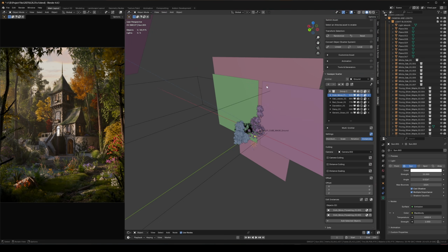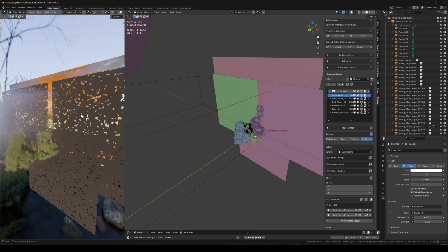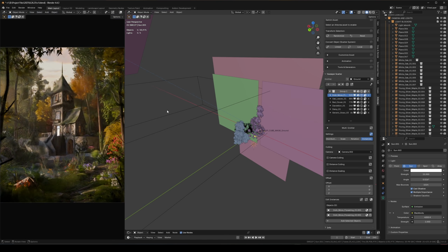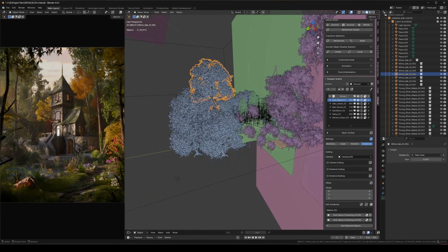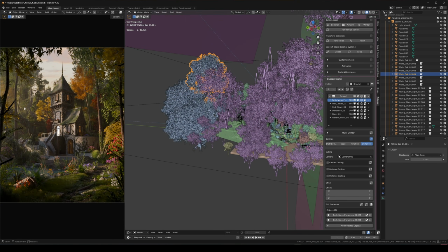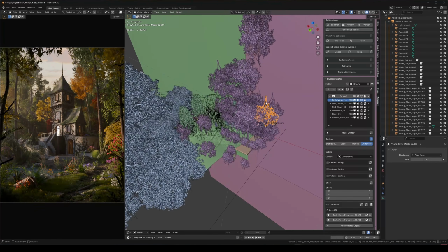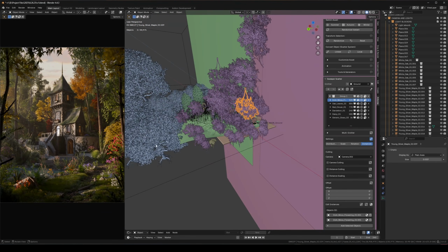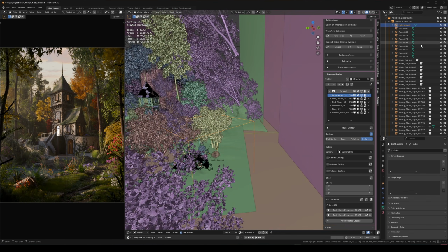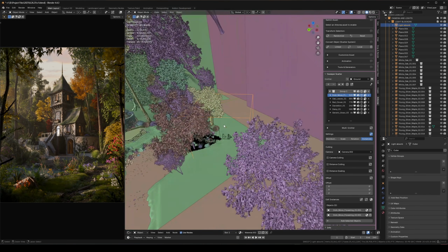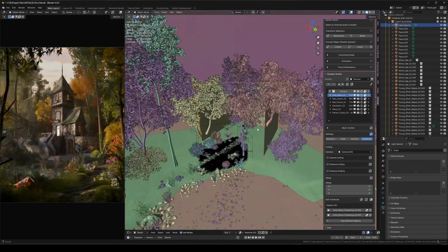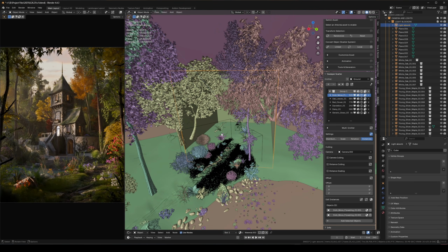So you can see I have all these planes right here, which, if I zoom back out, are just blocking a ton of the ambient light from the right side. I have these trees behind the scene as well, blocking some of the light down here and making the forest feel a little bit more full. Then I also have all these floating trees surrounding the scene, which is doing most of the work. And then I have this cube, the light absorption cube, which I actually face here. Let me put this as textured. I place this behind the camera and I delete the front face, so the camera is just surrounded by this cube.